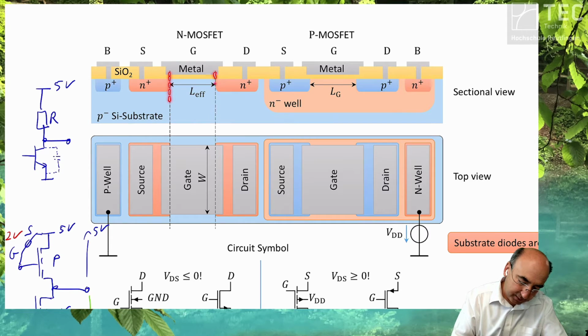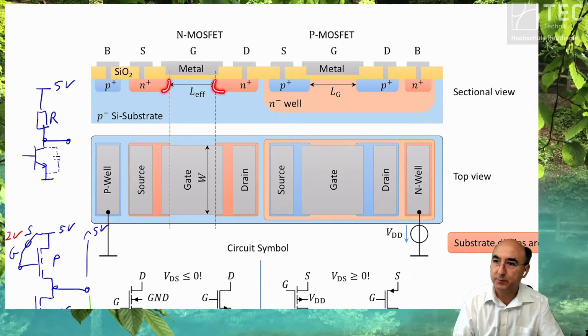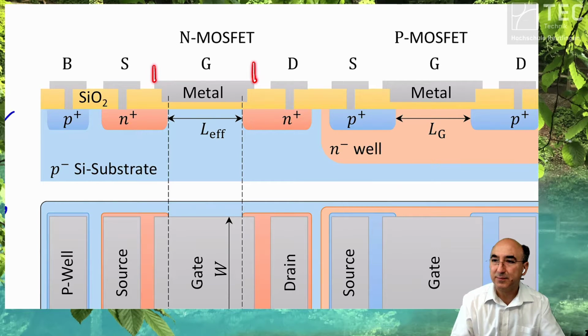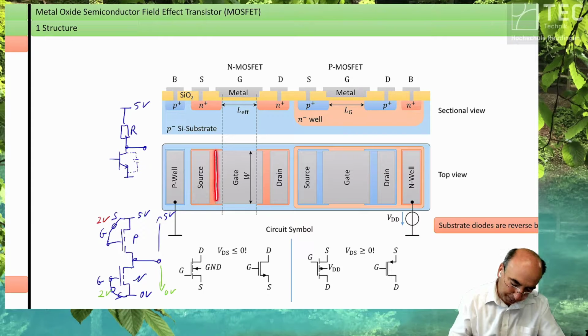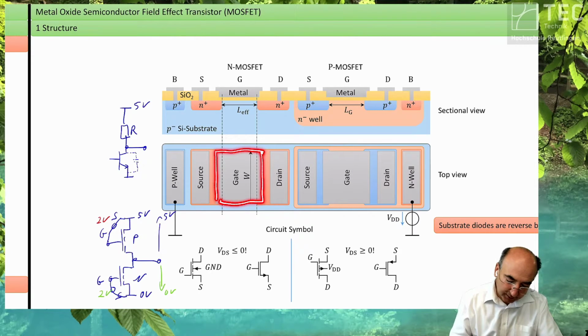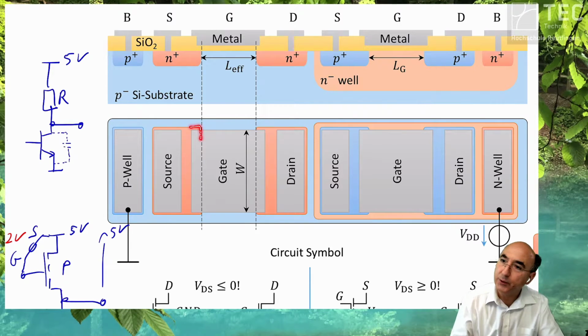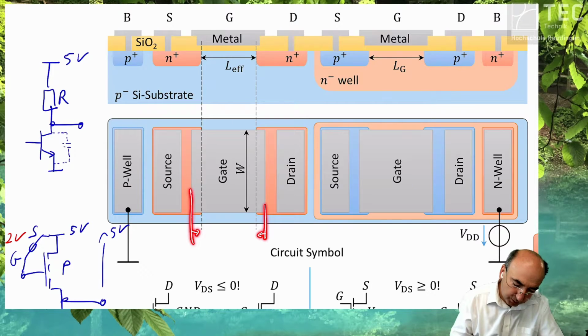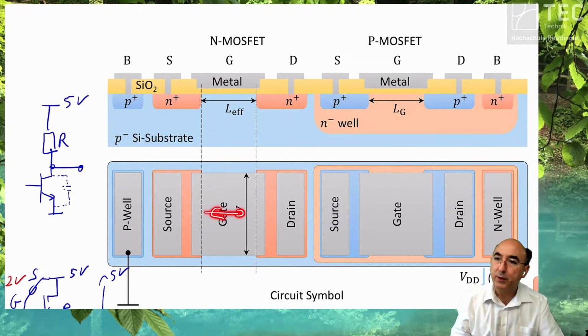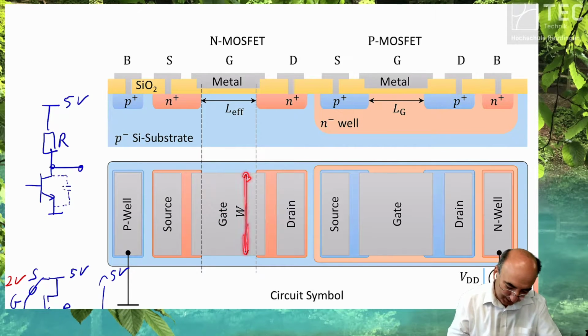We define the so-called gate length by the distance of these contact areas. That's the effective gate length. You, as a designer, you draw this gate length by putting this metal as a layer. You are the designer of these layers in the circuit diagram. And in the technology, due to the undercut, we learned why it has happened, the drawn length is reduced to the effective length. Okay, why do we call this L length, whereas this width is larger than the length?